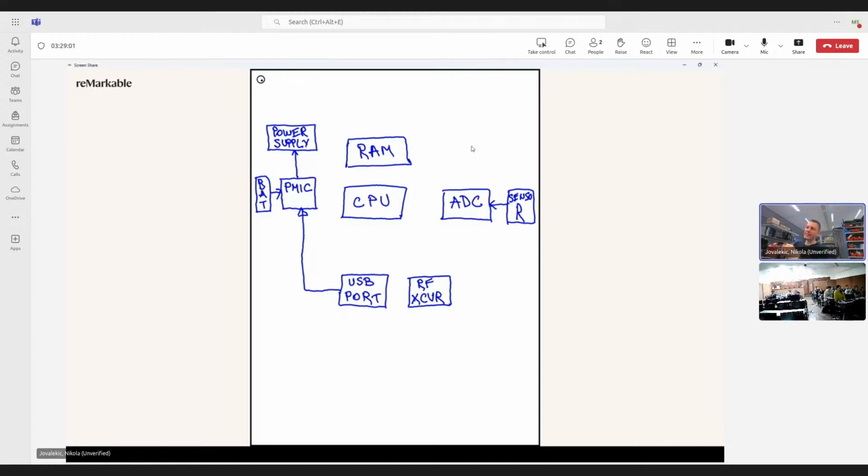But does the information 250 kilobits tell you something? Which kind of interface could you select? DMA? DMA, direct memory access. Okay. Well, you know what can be used, and what is usually used, is simple UART.